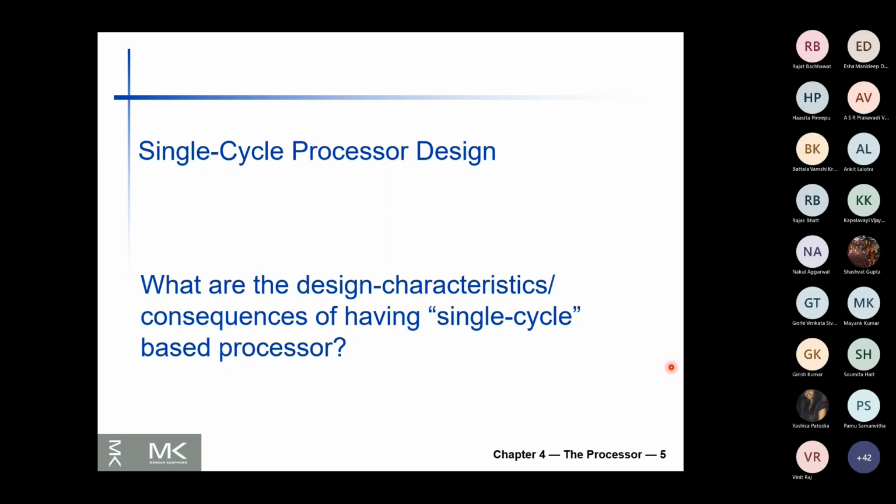Suppose I have a shift instruction. You know that in a shift instruction you can shift the content of a register by a number of bits. How do you implement it? I mean, shifting by say 5 bits or shifting by say 30 bits. So, barrel shifter. It's a combinatorial barrel shifter. Regardless of the amount of shift, you can implement it in one clock cycle. Otherwise, you have to do it sequentially.